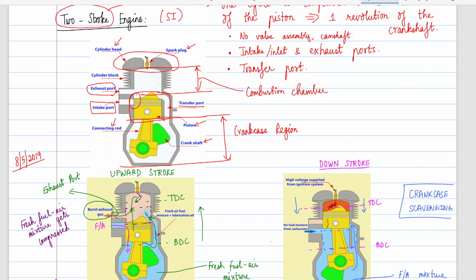How can we evaluate the efficiency of an EV gearbox? The idea is the same, power in, power out, right? Any efficiency definition is literally that, what we are putting in and what we are getting out of it. So you'll say how much power you are obtaining at the motor end and how much power you are obtaining just outside the gearbox.